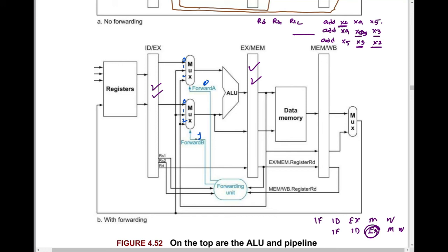So here we need to write, in this case again, the start instruction is in IDEX before starting the execution, and the first instruction is now stored in this memory write back register. So the same thing we'll write here, only we'll write: if memory write back dot RD is equal to IDEX dot RS1, in this case forward A should be 1, right?